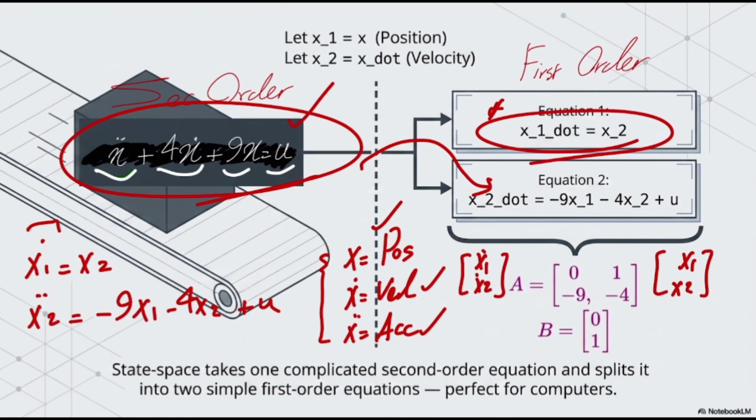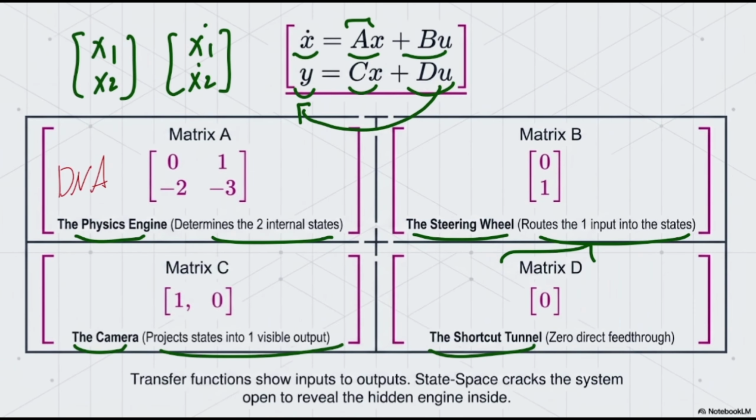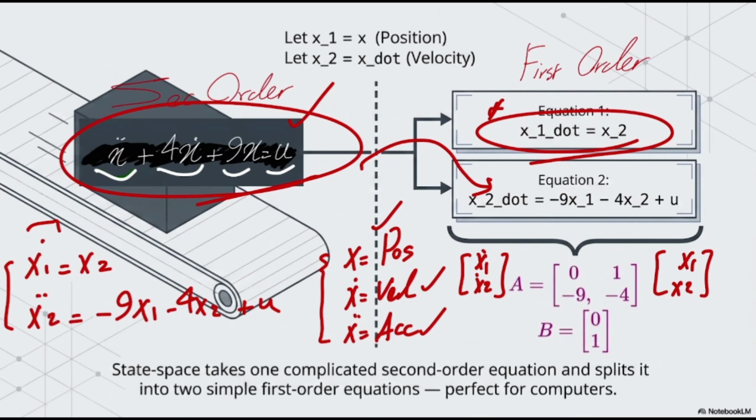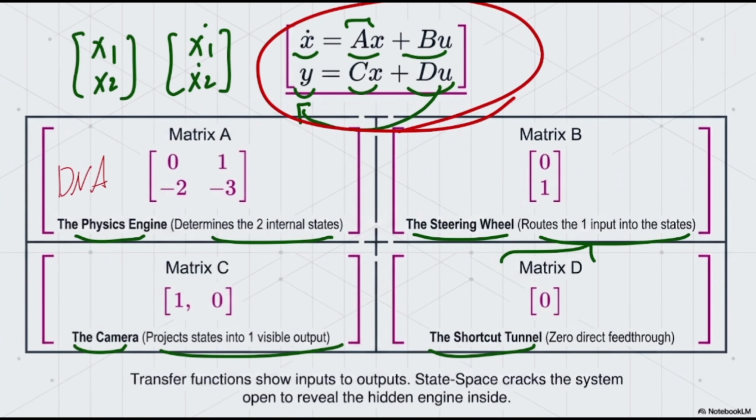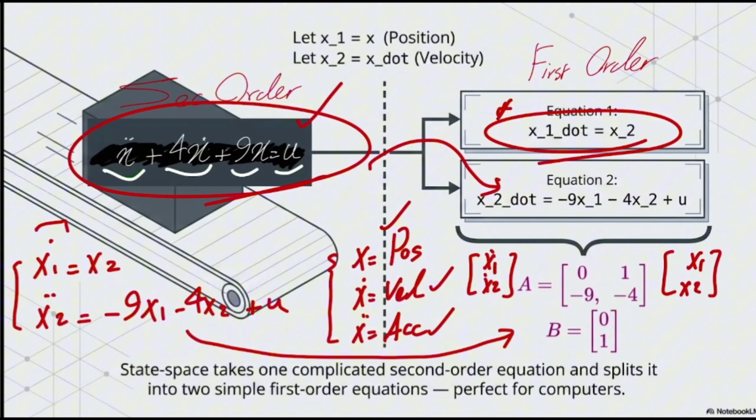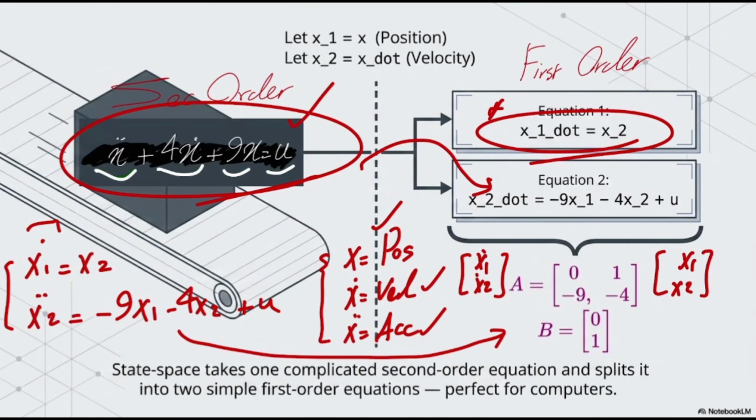So what am I trying to figure out here? At this point, I'm trying to convert this, based on these two state space equations, to the standard form, where I would like to find my matrices A, B, C, and D, because those values are very important. If I compare this to the formula that we just saw, my A first row is going to be 0 and 1, because the coefficient for x1 is 0 and the coefficient for x2 is 1.